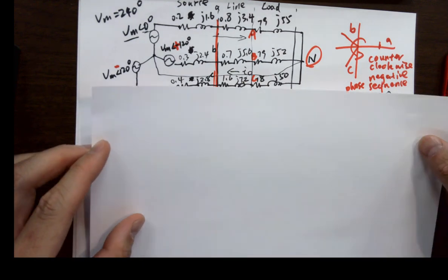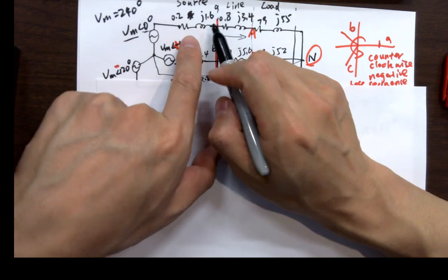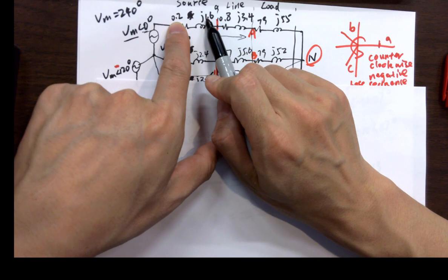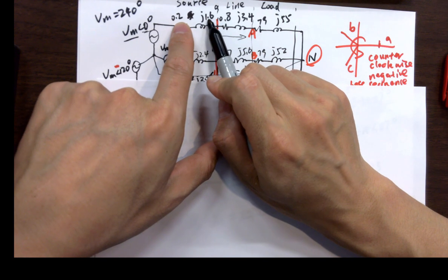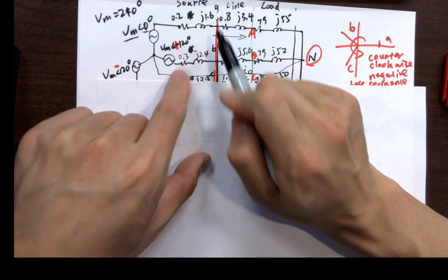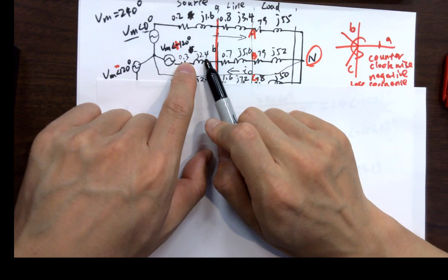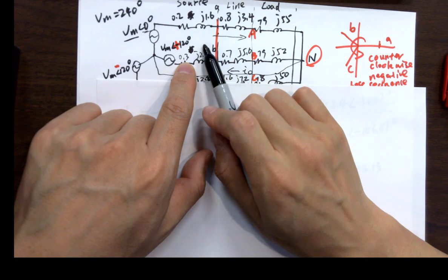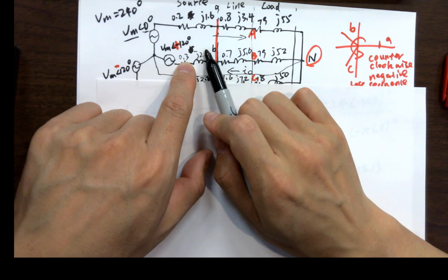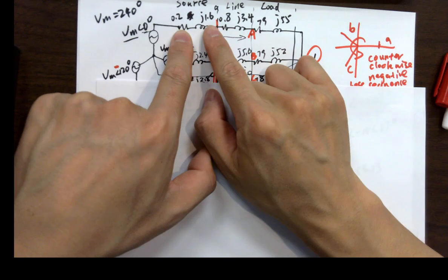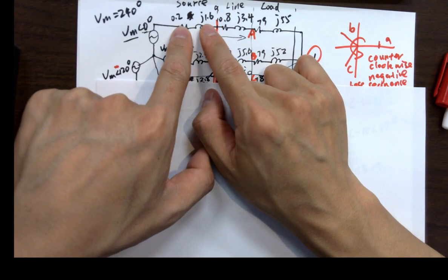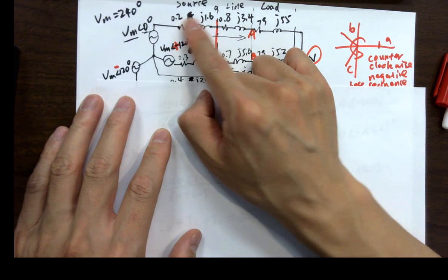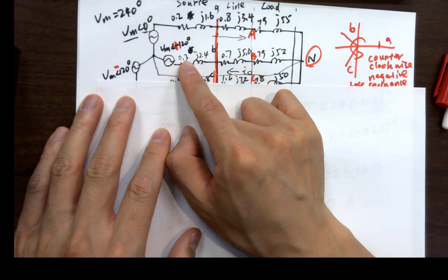The phase is probably fine, because if you look at the division, the imaginary part divided by the real part gives you the arctangent angle. So this becomes 8, and same here. So it's probably causing the same phase shift. I don't know if that makes sense for you guys. The impedance is causing the same phase shift, because if you calculate the angle here, this divided by this is 8. 2.4 divided by 0.3 is also 8.